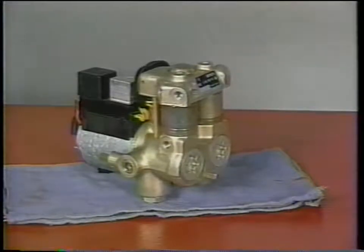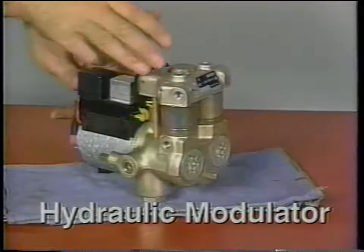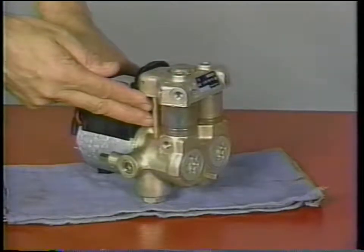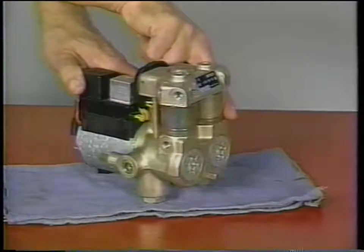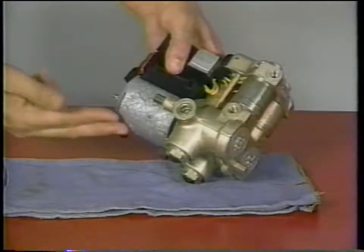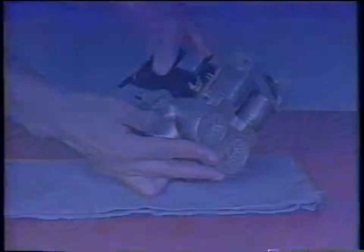The system's hydraulic modulator contains 3 solenoid valves. Each valve is a normally open 3-position spring-loaded valve. 2 solenoid valves control the front calipers. The other valve controls the rear. The modulator also contains the electric motor and pump assembly and 2 accumulators.